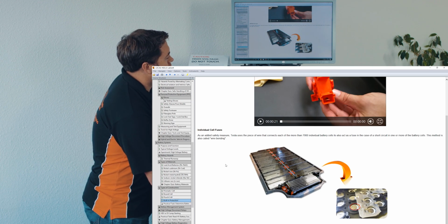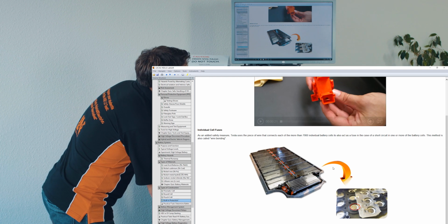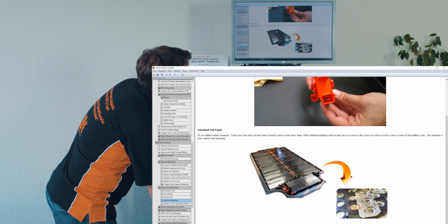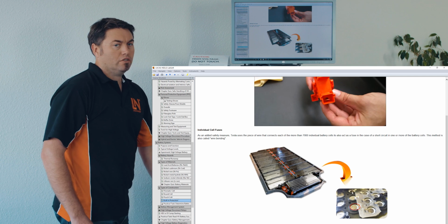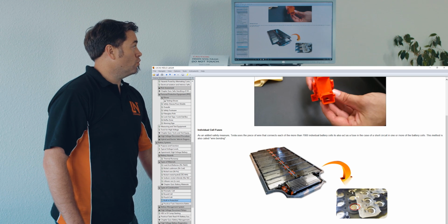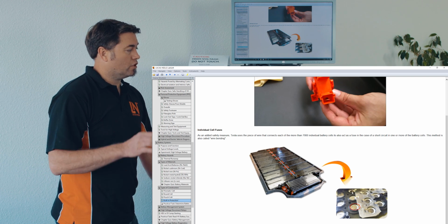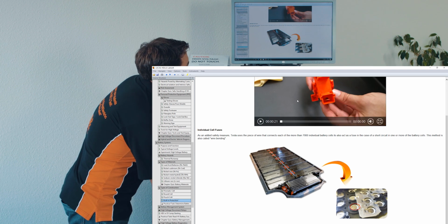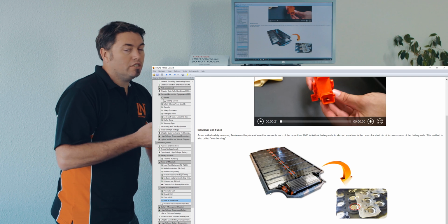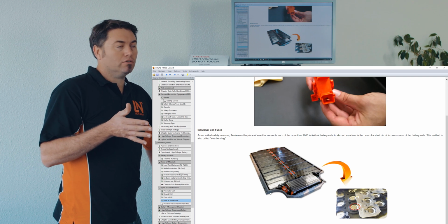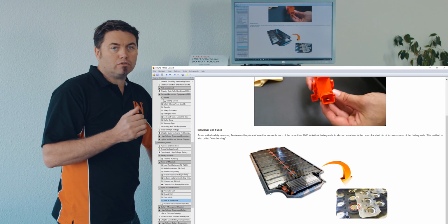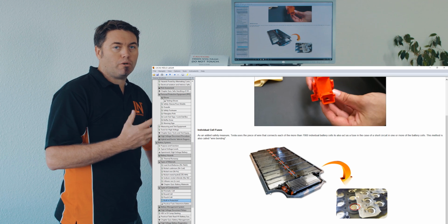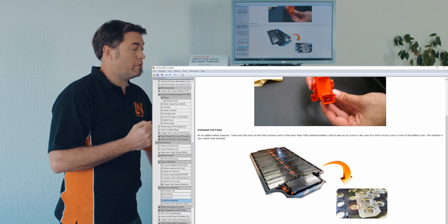If you look on the Tesla version, we're actually seeing that there are tiny little fuses on every single one of these cells, and that's called wire bonding. So if there's a short circuit within that individual cell, that will just blow that one fuse. And because there are so many in series and parallel, by having one of those drop out, we will drop capacity, but we won't drop complete voltage or thereabouts.